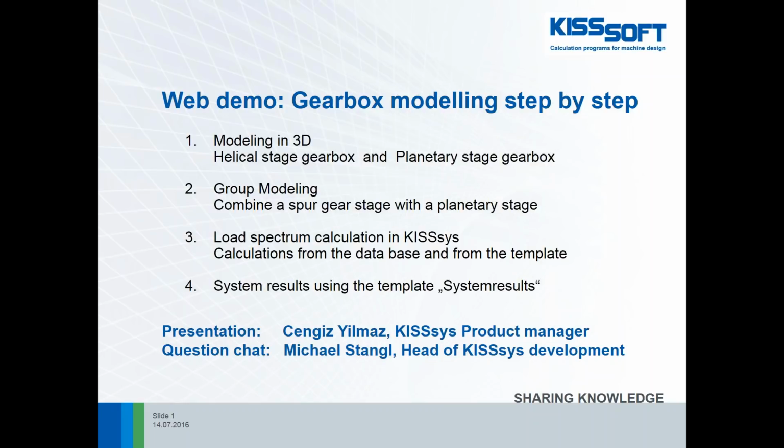After these modeling tasks, we will go to the load spectrum calculation, and I will show you two options in KISSsys for how to calculate with the load spectrum. Finally, we will finalize the demo with additional results, with the auxiliary results table, where we will have the system calculations and the results in the system like mass, inertia, energy, and backlash.